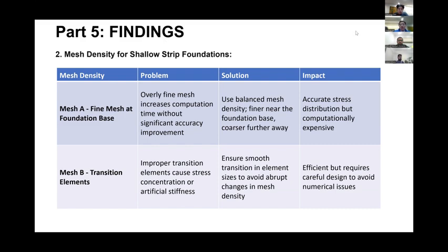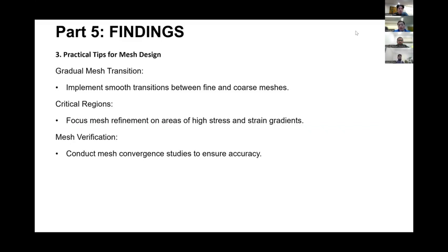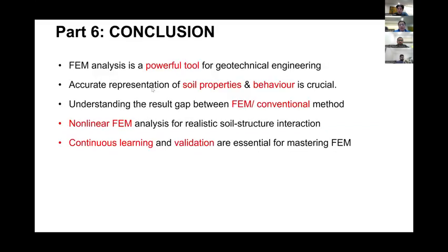From our practice, we have some tips for the mesh design. First is gradual mesh transition. The second is the critical regions, where we need to focus on some areas. The third is mesh verification, where we conduct a convergence study to ensure the accuracy.